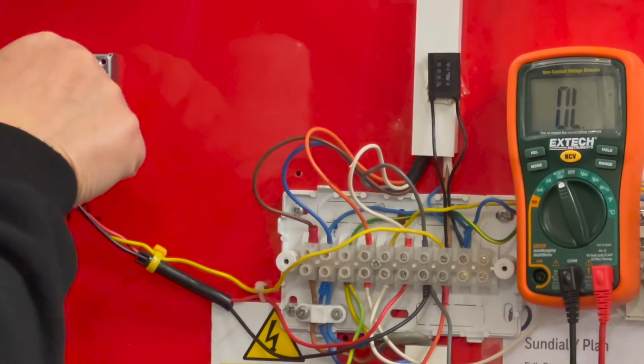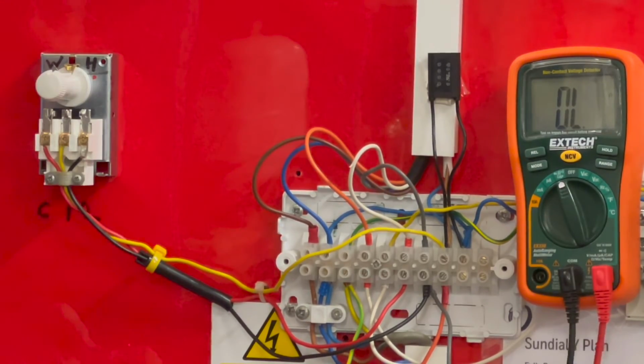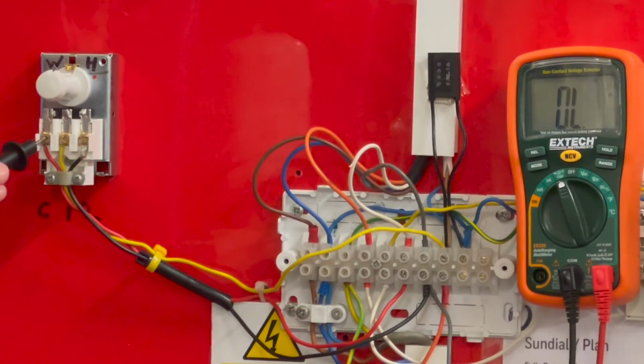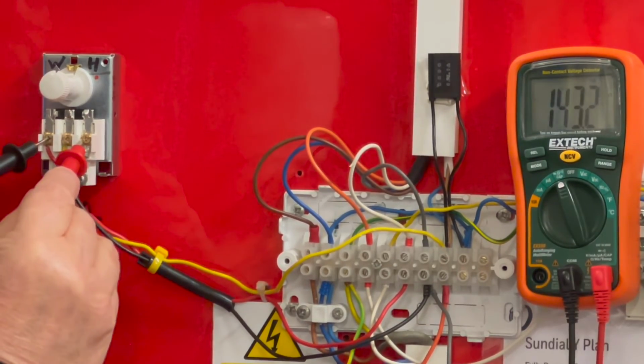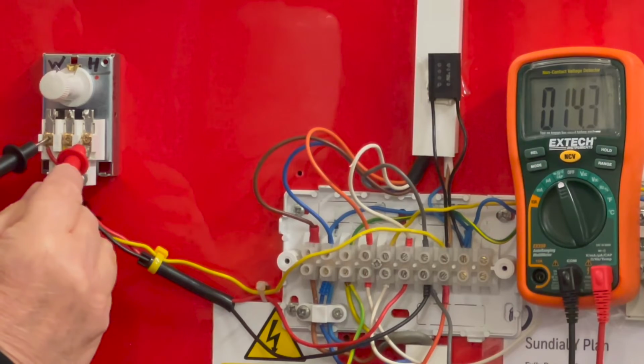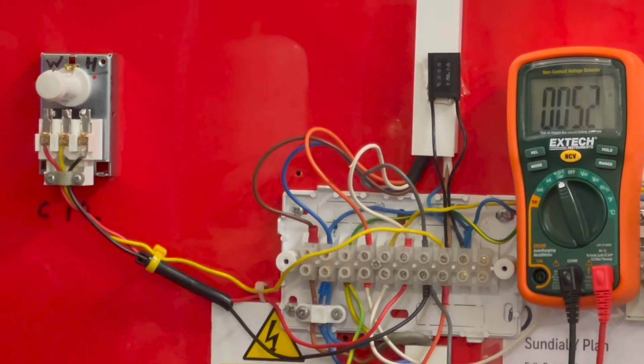And then let's put it over to the heating, and we should have the reverse. So we'll go common to 1 ought to be silent, yes, and to 2, there we are. And now we're in central heating mode. So this is a really good quick test. Whenever you go to this, you can see whether the cylinder stat is working correctly or not.